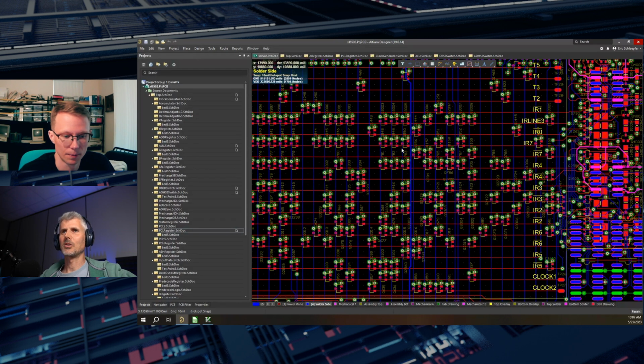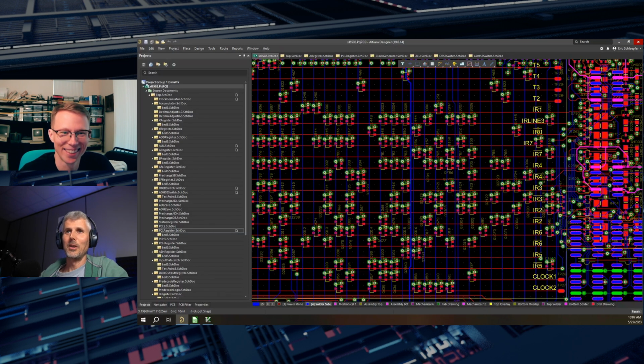Because this is all NMOS, when the MOSFET's turned on, that's when the resistor is drawing the current. So what is the power draw then? It varies depending on what you're doing, but typically it's around 2.5 amps. Pretty chunky. Yeah, pretty chunky. So when you turned your power supply on and it went way past that, you thought, well, that's a little high. Yeah.